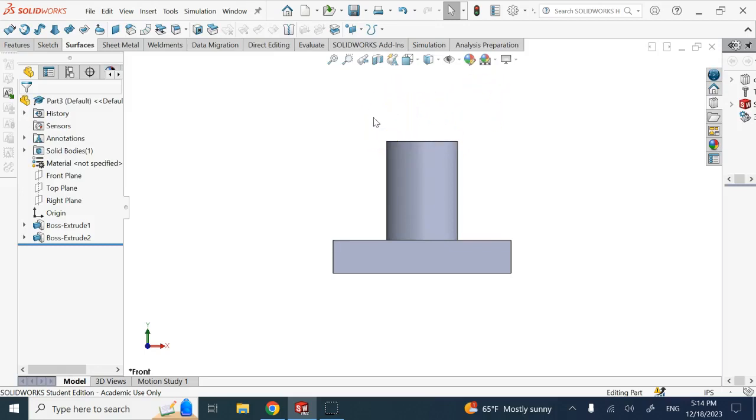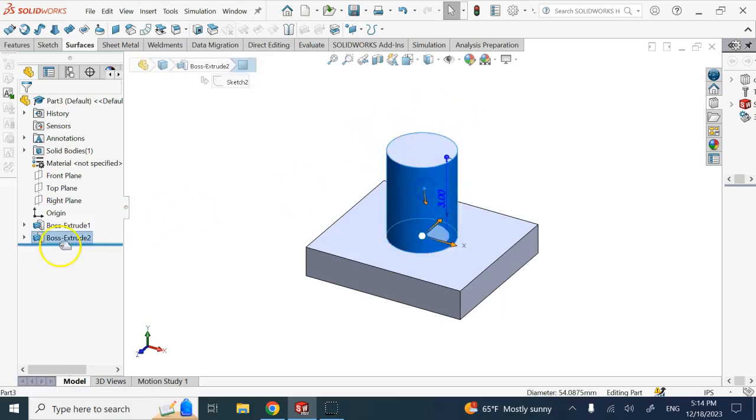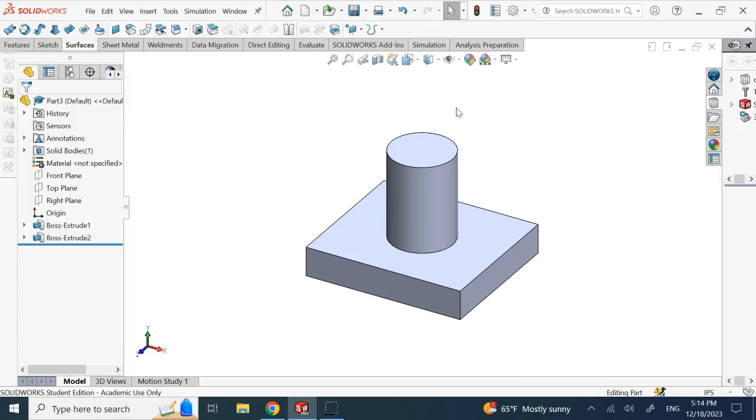Okay, can you do that? Yes, of course. So one way is to create a surface and then let this extension, instead of going at a blind of 3 inches, extend until the surface. The other one is replace surface, which can do that.